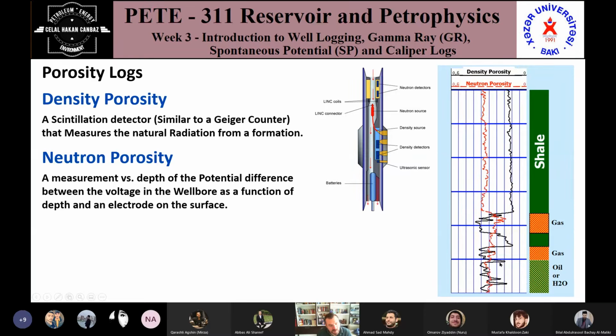This is actually more understandable between gas and oil. It shows just one peak. But with oil and water, according to the density difference, what happens? Because these are immiscible, there will be a transition zone between your oil and water content, right? So because of that, you are seeing these transitional zone changes here. Somewhere in here is a transition zone, and after that part, your water starts. So you can understand these types of things.